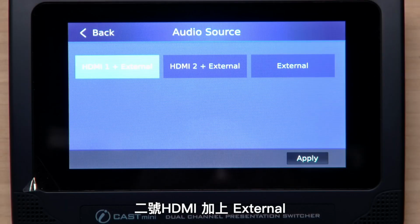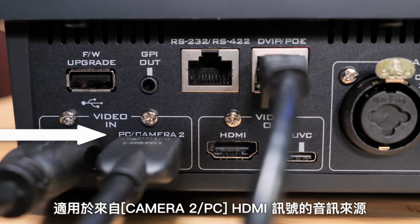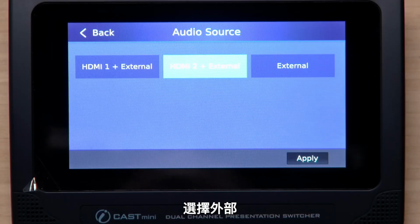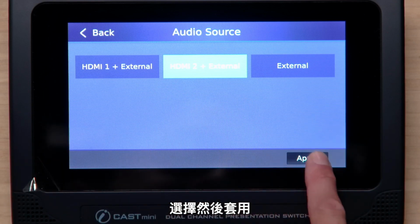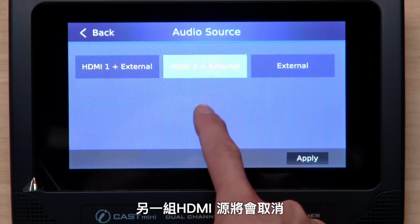HDMI 2 plus external is for an audio source embedded in the HDMI signal connected to the camera 2/PC input, in addition to the external audio from channel 1 and 2. Choosing external is to use the channel 1 and channel 2 audio only. Make a selection and press Apply. When choosing a HDMI source for audio, the other HDMI source will be disabled.